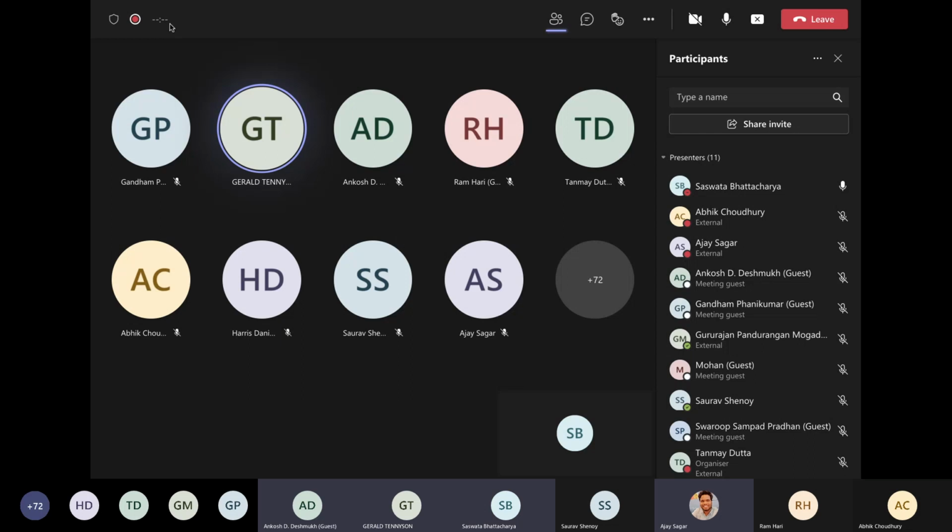Exactly, it can. That's what I am trying to say. But bainite basically is not diffusionless. So this will be a very appropriate code, right? We just have to include the multiple variants that are there in a typical bainitic structure, right? Correct.